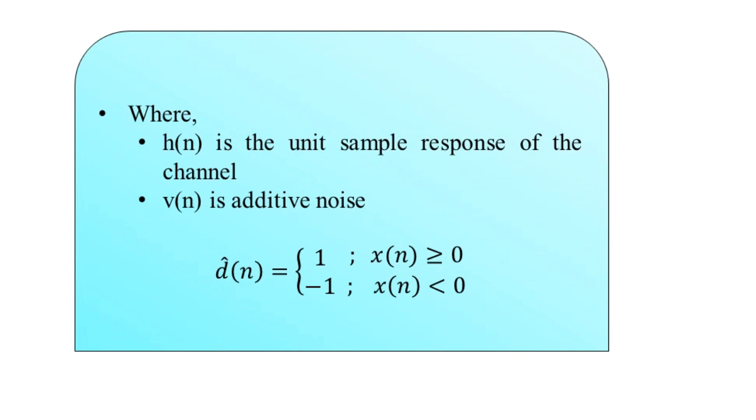Now, in order to reduce the chances of making an error, we want the perfect signal to be decoded at the receiving end. The receiver will employ the equalizer. So this is our topic of interest, channel equalization, in order to reduce the effects of channel distortion. And since the precise characteristics of the channel are practically unknown, and possibly time varying, the equalizer is typically an adaptive filter. This is the use of the adaptive filter design for channel equalization.